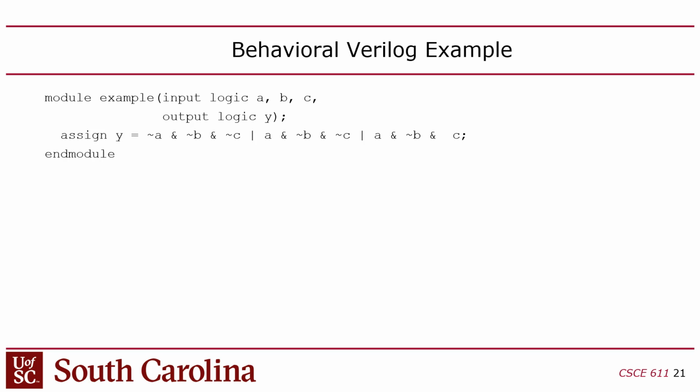because this language is independent of the underlying technology that I'm using, there is no delay here. This is purely behavioral. This is the behavioral implementation, but there are no assumptions here about the underlying technology. So there's no delay. Well, there is a delay, but it's an epsilon delay, meaning that it's a non-zero delay. So when I change those inputs, the output will change instantaneously after I advance the simulation by any amount of time. You guys with me?